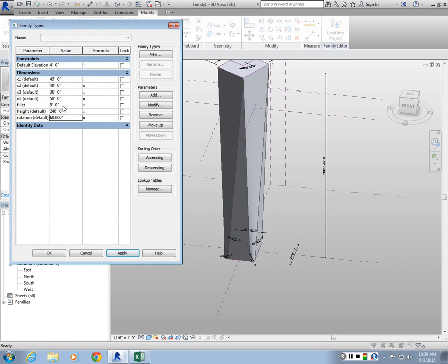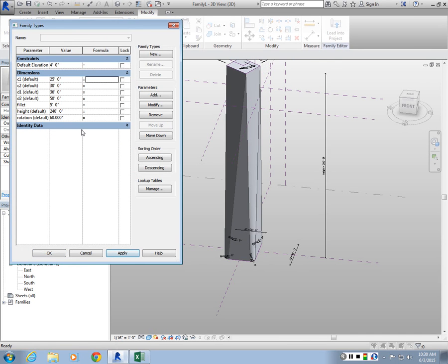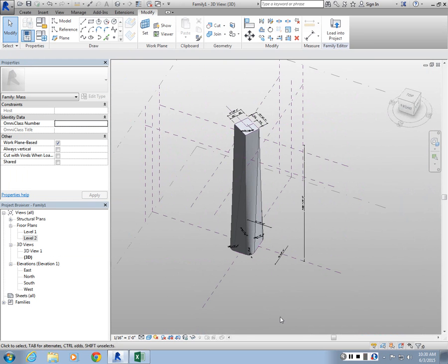So change the rotation, change these dimensions, so I can make this 30, slimmer on top, this one 25. Right? Just a simple flexible model I can use. This guy's 40. Let's change the fillet to 10. So that radius increases as well. So it's kind of a ruled surface here, because it's actually conic. There's a radius here and then it tapers to a flat geometry. So I got something like that.